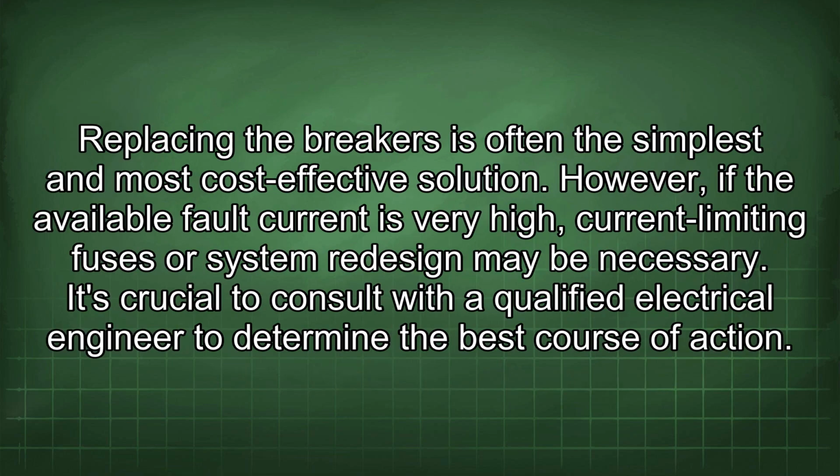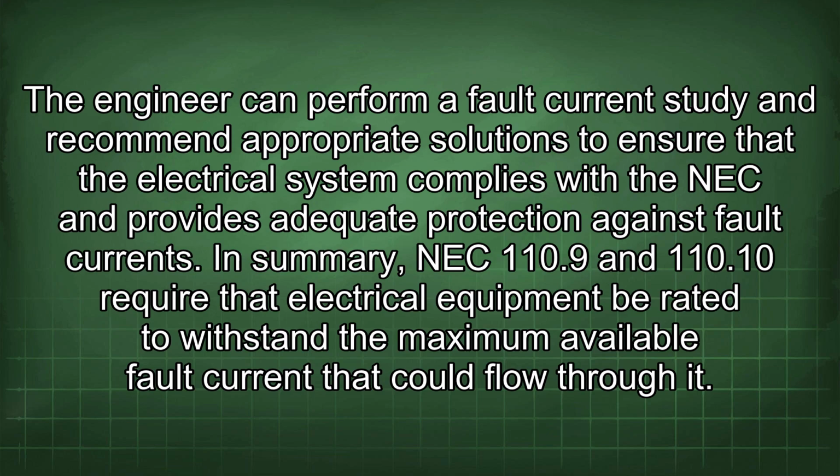Replacing the breakers is often the simplest and most cost-effective solution. However, if the available fault current is very high, current limiting fuses or system redesign may be necessary. It's crucial to consult with a qualified electrical engineer to determine the best course of action. The engineer can perform a fault current study and recommend appropriate solutions to ensure that the electrical system complies with the NEC and provides adequate protection against fault currents.